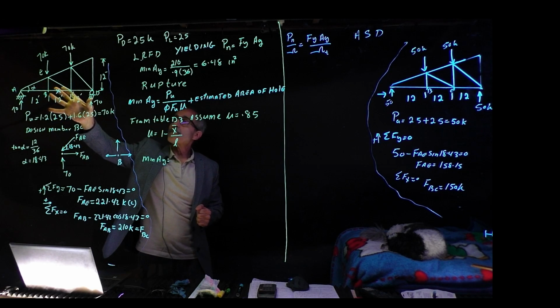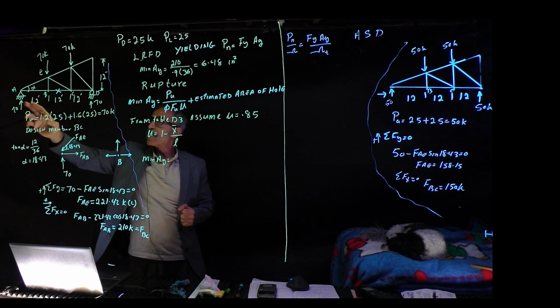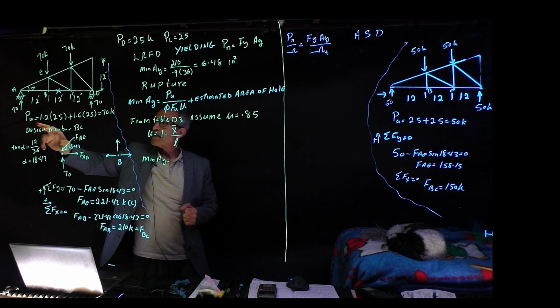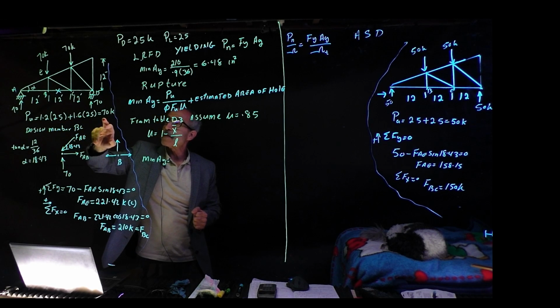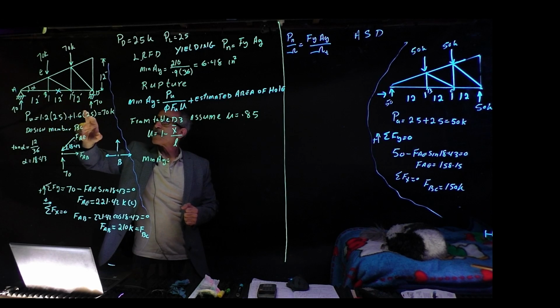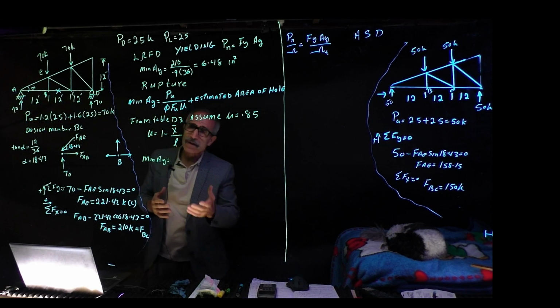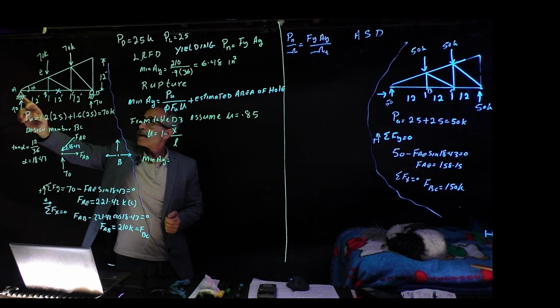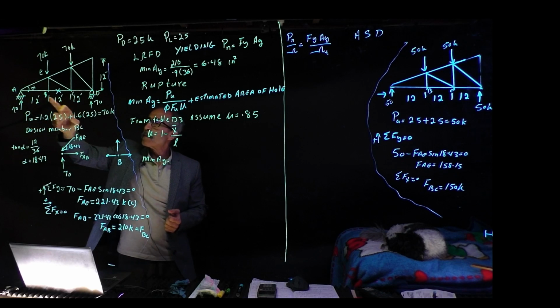First thing we're going to do, we're going to calculate the load per LRFD, which is Pu equals 1.2 times dead load plus 1.6 times live load. That became 70. Because it's a symmetrical reaction, it's 70 here, 70 there. Then I'm going to do a truss analysis. I just made a video prior to this one. Do a method of joints analysis to calculate the member forces.